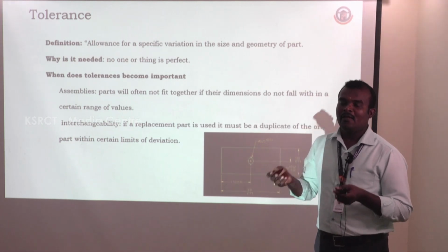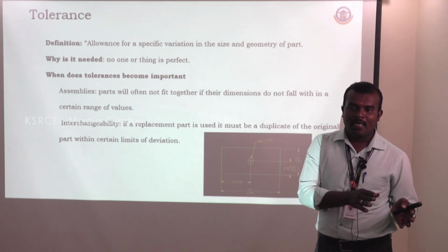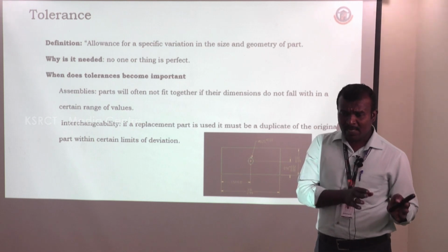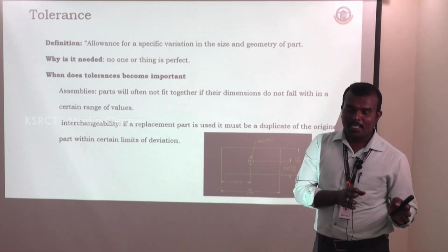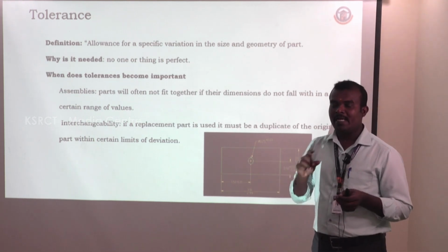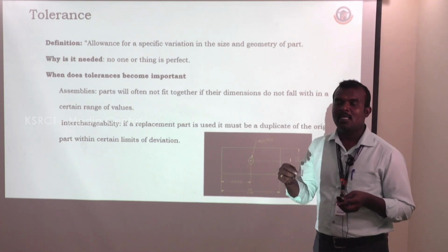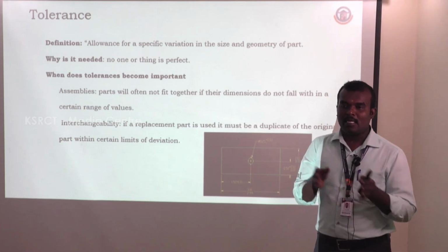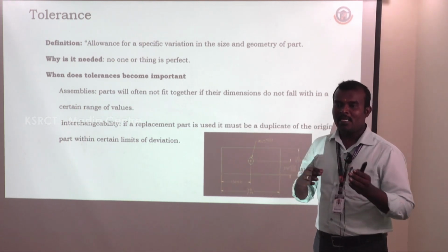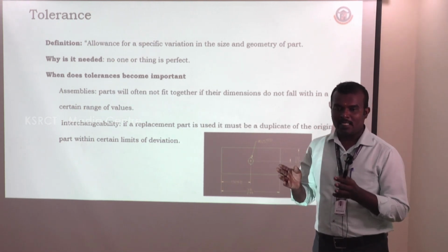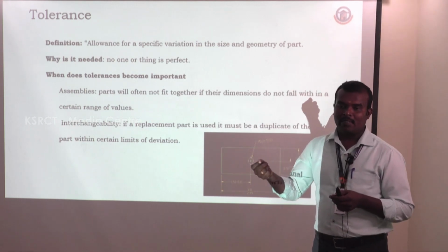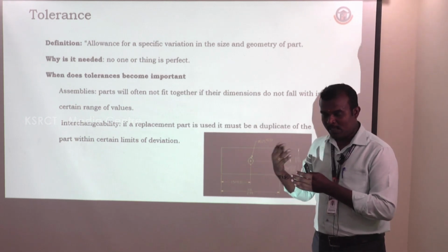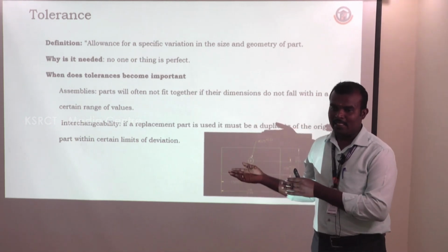If we have to manufacture a component on a lathe, it requires some allowance. Depending upon the machining, the quality will be different. Whether we have to do the facing operation or the turning operation, in a lathe or in a CNC, the difference will occur. In CNC we can achieve micron level, but in a lathe we cannot achieve micron level, because it depends upon the specification or the requirements.